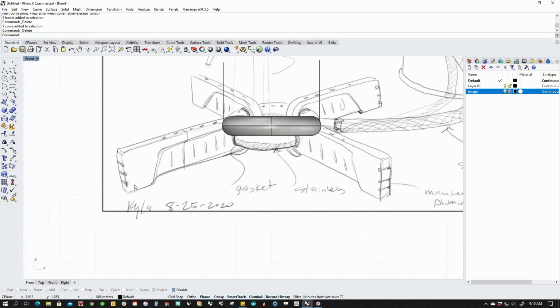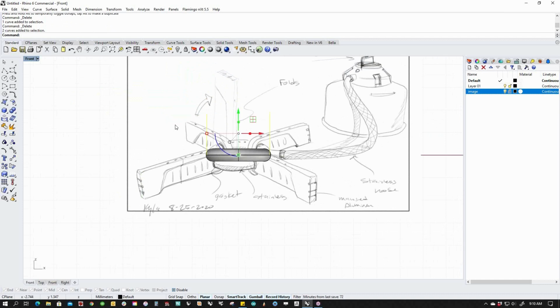So I also know, so if I go 4 inches long, and then let's say, well, how big is this in this dimension? And the nice thing about this curve length is it allows you to get a non-oriented view, and you can see how long something is. So in this case, 1.22. Let's call it 1.25 inches, just for argument's sake. So we know our basic dimension here is going to be 1.25 inches high by about 4 inches long.